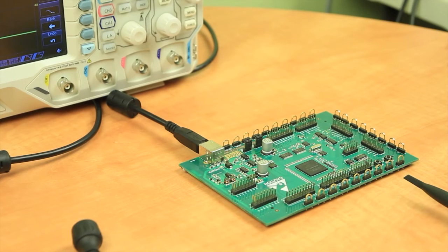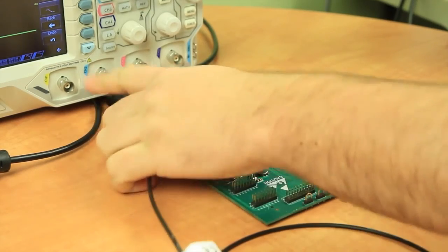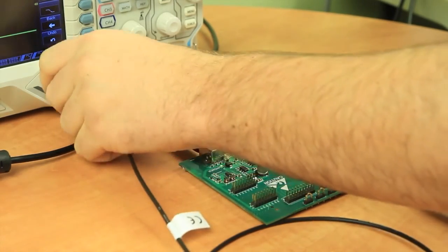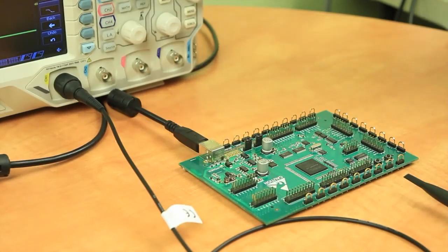To demonstrate how to probe around with the probe itself, to start off, I'm going to connect our probe by pushing on the slot in the scope itself. There are 2 pins on here, so you have to line it up before rotating on. Once you push it in, you then rotate it, and the probe is then attached.